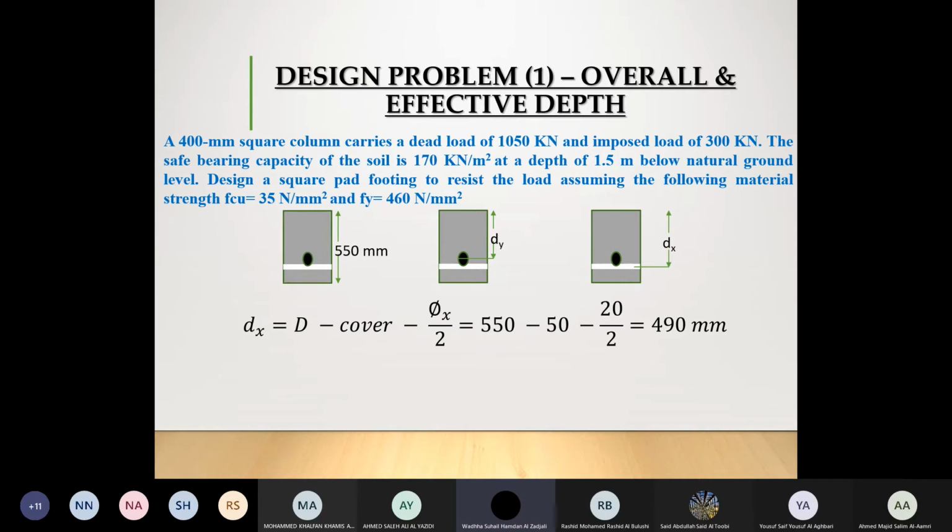Foundation. Okay. So now the foundation is going to carry more loads. If the foundation is going to carry more loads, then of course eventually the bending moment is going to be higher, because we said whenever the load is increasing, the bending moment will increase. Whenever the bending moment increases, your reinforcement will increase. Whenever your reinforcement increases, your diameter will increase. Do you agree with me? Do you agree that it's a sequence?